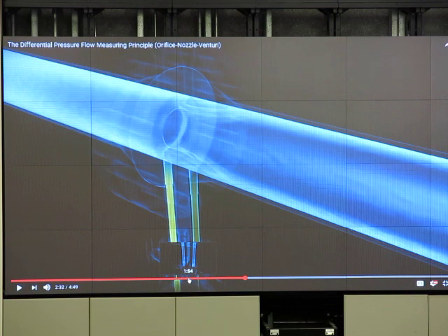Are we going to use the one that has a very small hole, or the one that has a big hole? How do we decide that? There are several kinds of holes for the orifice plate, right? It depends on flow rate. How much do we flow? If we flow a lot and we use the one that has a very small hole, this means it can measure, but it creates too much pressure drop. Okay, you have 50 psi pressure drop across just the flow meter.